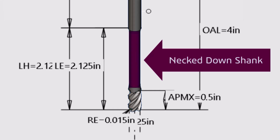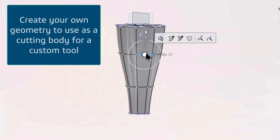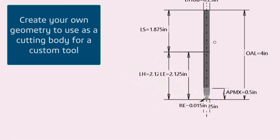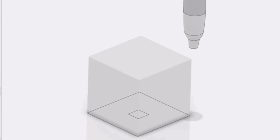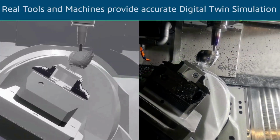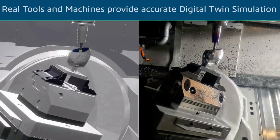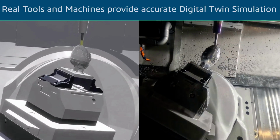User representations also provide accurate cutting simulation. Because we carefully define cutting and non-cutting zones, we can make use of custom tools and yield real toolpath results, collisions, and other interactions you can expect from your custom tool. It's not always necessary, but user representations fill in the gaps where user-generated tools come up short and maintain a virtual twin for your machining environment.